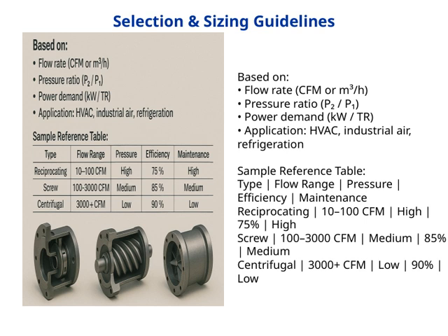Finally, centrifugal compressors are suited for even larger flow rates, over 3,000 CFM, with lower pressure ratios and the highest efficiency at around 90%, and they generally demand less maintenance. Understanding these guidelines helps us make informed choices tailored to each specific application, ensuring we select equipment that's efficient, reliable, and suited to the operational demands at hand.